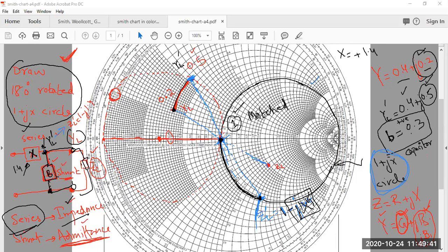So now, from the Smith chart perspective, what has happened? You need to understand this point. We started with our load at this point. Our load was at this point. And because it was not at the center, it directly tells us that our circuit is mismatched. But with the help of a circuit which consists of, of course, B was a capacitor.